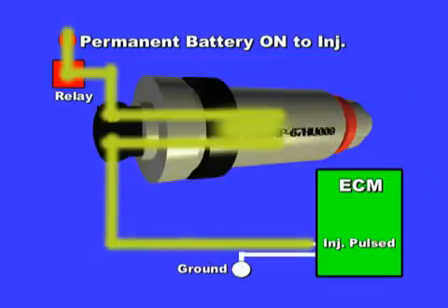If you get an OBD2 injector open code P0200 to P0212, do as follows. The ECM always monitors the injector wire. 12 volts flow from the battery to the relay and through the injector. It then returns through the injector coil to the ECM wire.